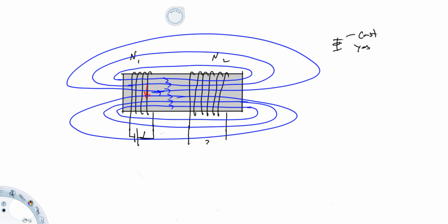So what do we expect for an output voltage here? And the answer is nothing, because by Faraday's law of induction, remember, induced voltage is equal to the change in magnetic flux over change in time. Now, the way I'm formulating this right now, this would be per loop. I'll talk about how the number of loops comes into play in a minute. Long story short, a DC voltage here gives no output.